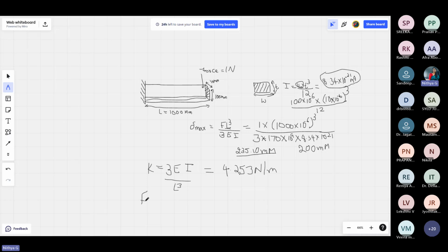So what is resonant frequency given as? Fr is equal to 1 by 2 pi root of K by M effective. M effective is the effective mass, because we know that cantilever beam is fixed at one end and not all the body of the cantilever beam bends for the applied pressure, right? There is an effective mass that only is deflected, whereas the other part of the body is constrained to move. So effective mass gives us the mass that is actually deflecting.